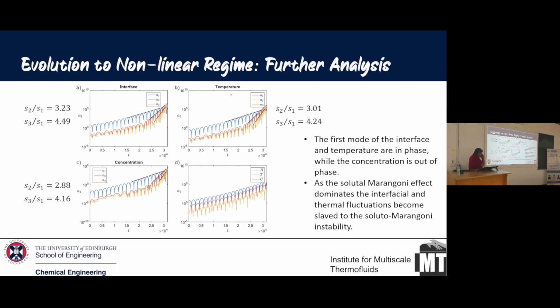What we also do is capture the height of the interface, or the height of the amplitudes, with respect to time. Basically I look at one wave. I start from a single wave, okay? This is my primary mode, and I look at the amplitude and how it grows. At some point it might grow in this way, so this is how your growth rate is. I then take the other harmonics. I take a Fourier transform and find out what the lower order harmonics are.